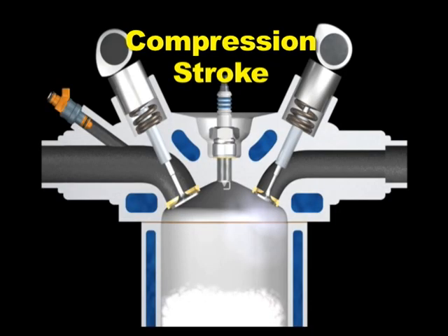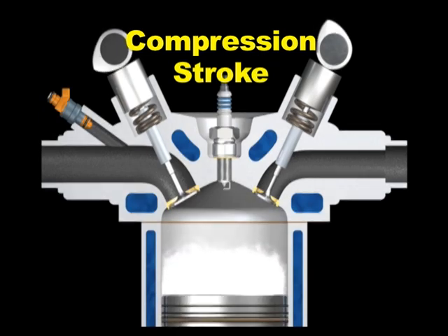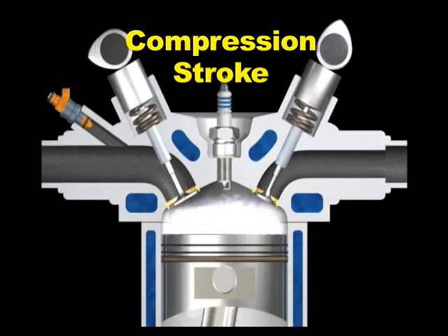The compression stroke prepares the air-fuel mixture for combustion. With both valves closed, the piston slides upward and compresses the trapped air-fuel mixture.